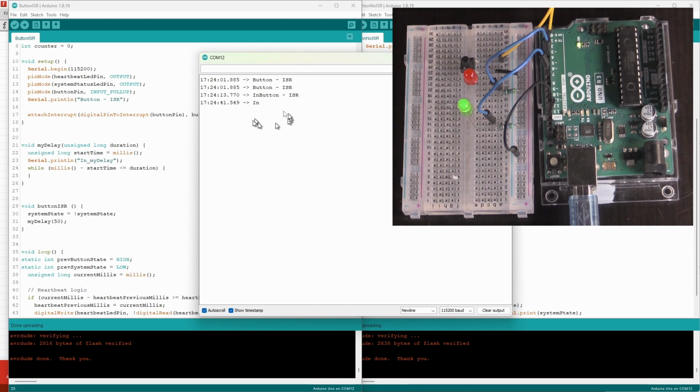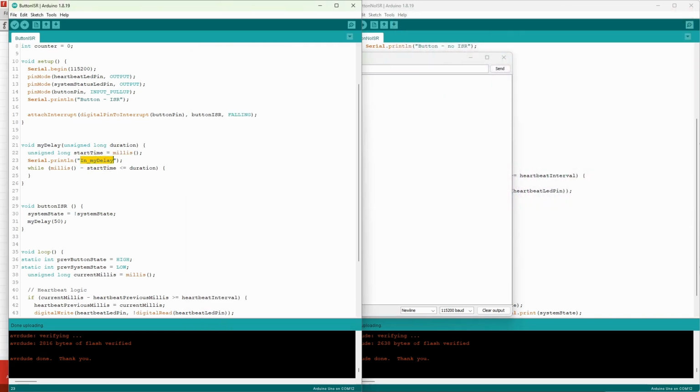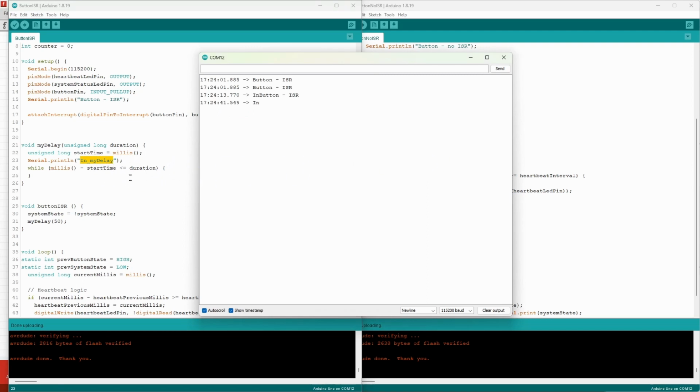And that's to do with the way that the serial object works and how it uses interrupts. But essentially what's happening is this message here is being stored in a little buffer, and if the communications is not doing anything, or it's ready to receive the next character, it'll put the first character in, which is the I. The instant that that happens, it's empty. The hardware takes that character and starts sending it off to wherever it sends it, and so it's empty.